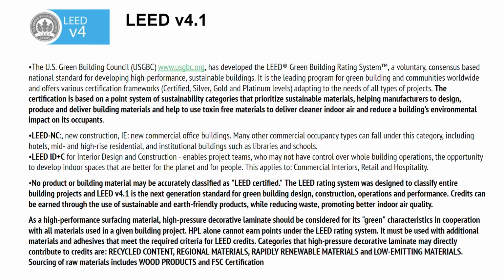HPL alone cannot earn points under the LEED rating system. It must be used with additional materials and adhesives that meet the required criteria for the LEED credits. Categories that high-pressure decorative laminate may directly contribute to are recycled content, regional materials, rapidly renewable materials, and low-emitting materials. Sourcing of raw materials includes wood products and FSC certification.